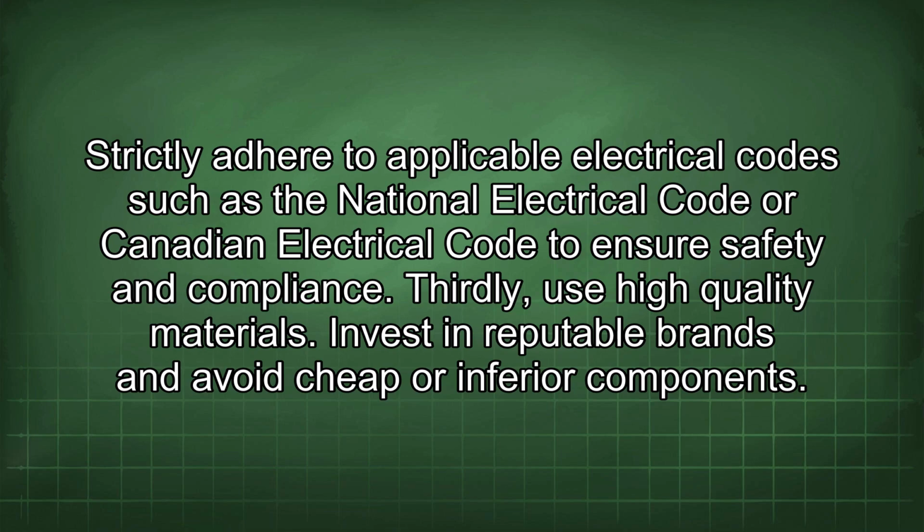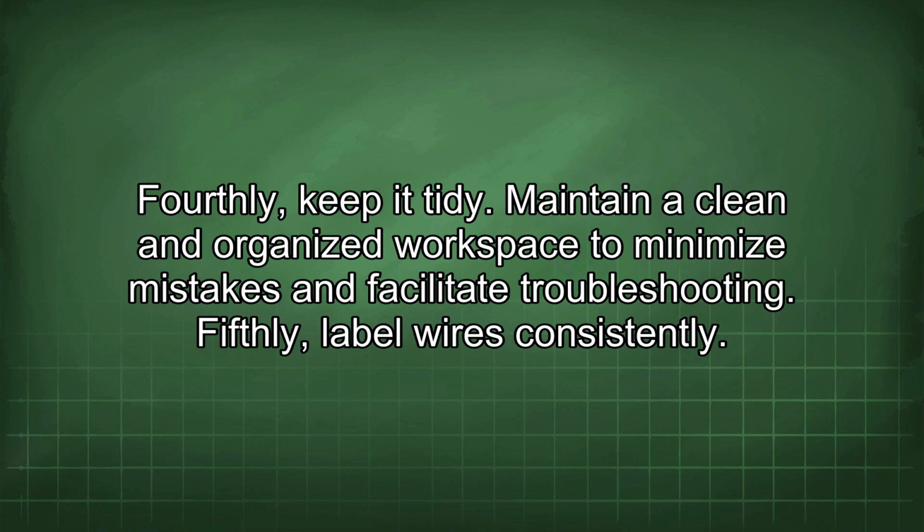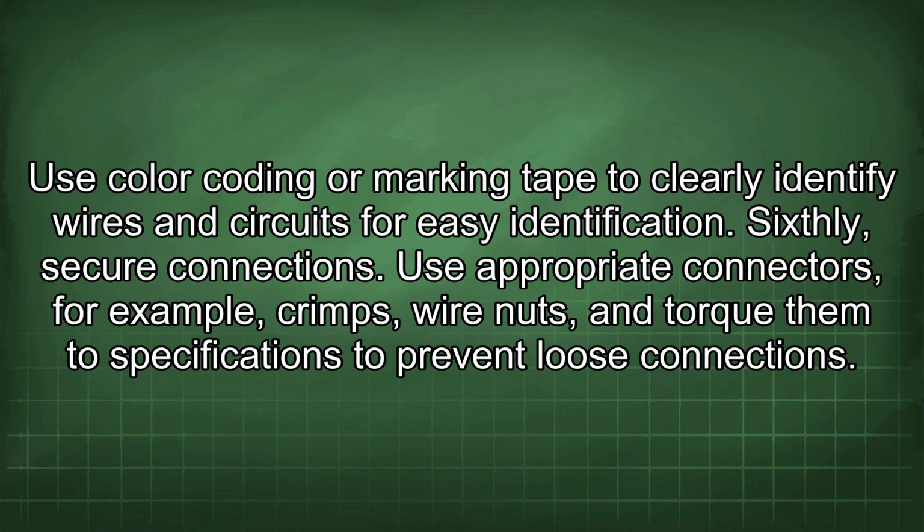Thirdly, use high-quality materials. Invest in reputable brands and avoid cheap or inferior components. Fourthly, keep it tidy. Maintain a clean and organized workspace to minimize mistakes and facilitate troubleshooting. Fifthly, label wires consistently. Use color coding or marking tape to clearly identify wires and circuits for easy identification.